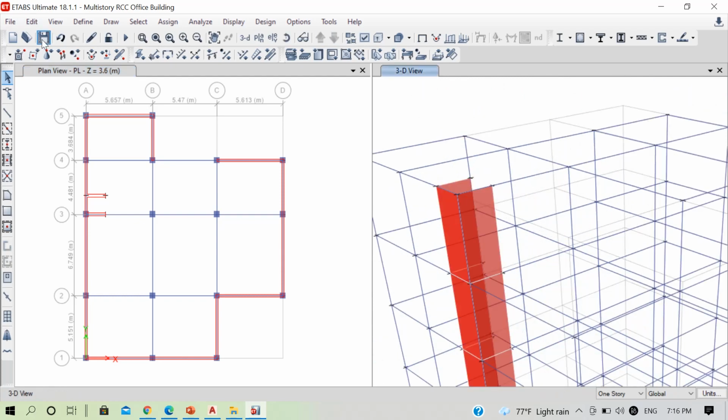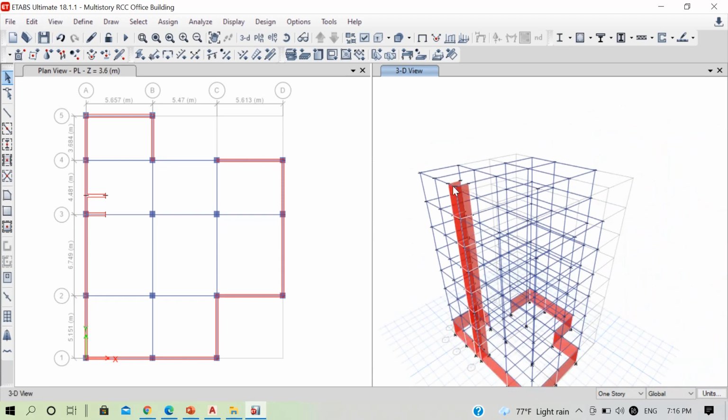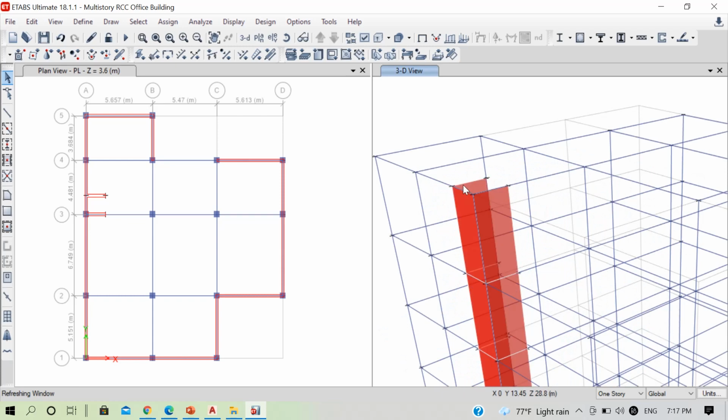You can see that our lift shaft or the shear wall for our lift core ended here. But many a times what happens is that you need more space above this topmost floor, known as headroom, for fixing these different mechanical equipments of lift wall. So you may have to now construct these lift walls above these floors also for a certain height. Let us say that that height is 1.2 meter for now.